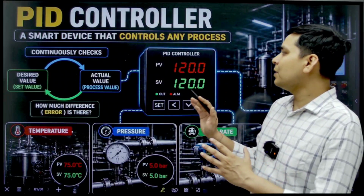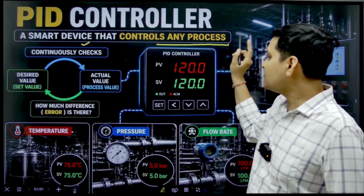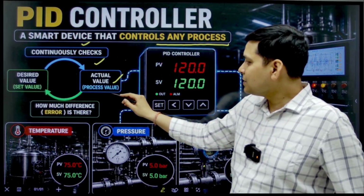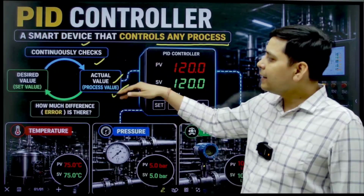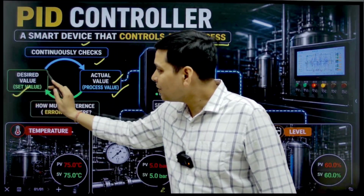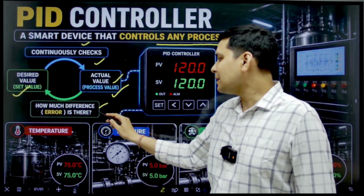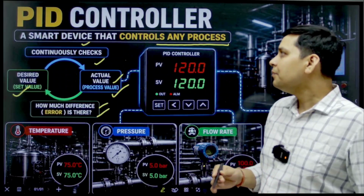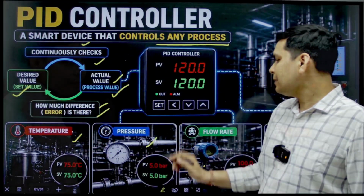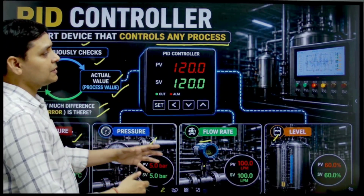Look friends, a PID controller is a smart device that controls any process. It continuously checks the actual value, that is the process value or process variable, and compares it with the set value or set point, and it calculates how much difference there is, that means how much error there is. A PID controller is used for temperature measurement, pressure measurement, flow measurement, level measurement, and any other measurements.